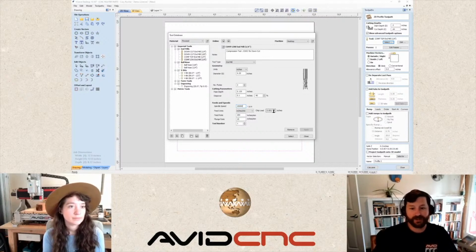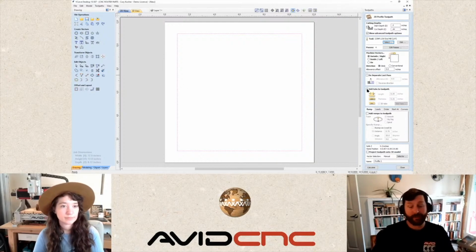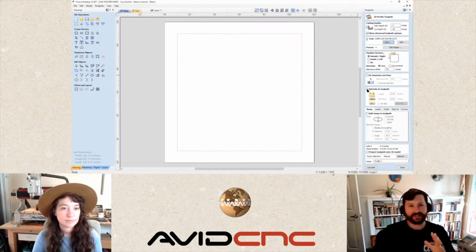And in this instance, a 0.005 inch tip is what our target is. So let's go ahead and select that. And because we are doing the outside, we don't need a separate last pass, but this is going to be full depth at this point. And so, Sami, why don't you tell us a little about the tabs you like to use when you're machining plywood?